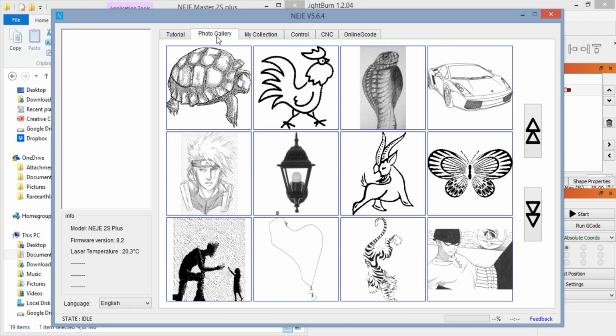There's two major ways that you can actually engrave something. One is called a raster engrave, so it fills in a picture, for instance, and one is called a vector engrave, and that basically traces a line. So the vector is a lot quicker because it basically just follows a bunch of lines, can get done in a very quick time, whereas a raster engraving literally goes line by line.